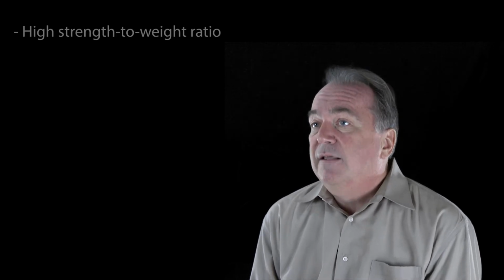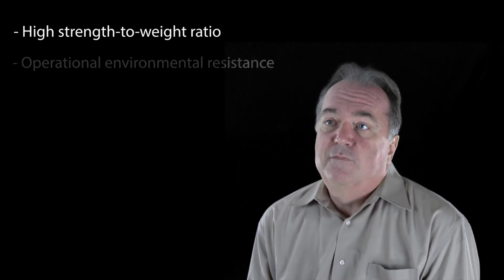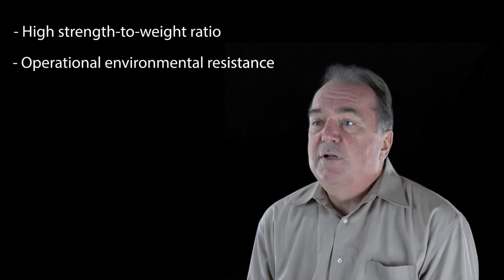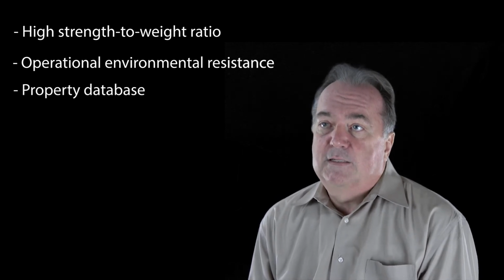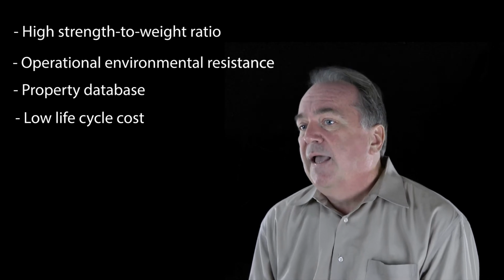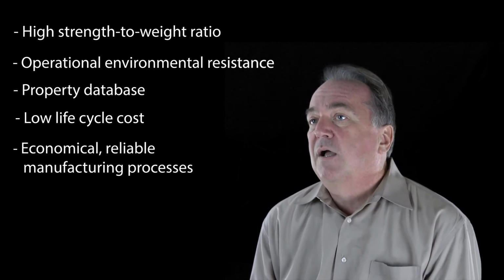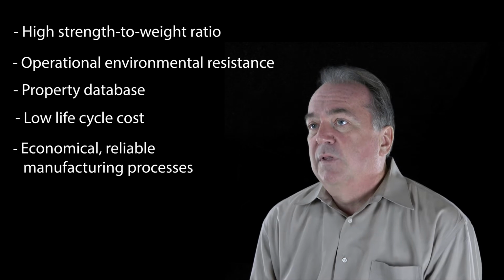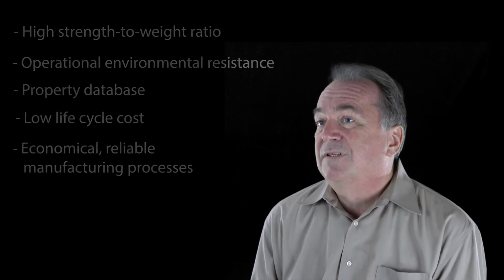These characteristics include, but are not limited to, high strength to weight ratio, operational environmental resistance, property database to support design activities, low life cycle costs compared to the traditional materials, and economical, reliable manufacturing processes. The key elements with the material are both to have the structural integrity required, as well as to have the low cost and low weight that is desirable for a DoD platform application.